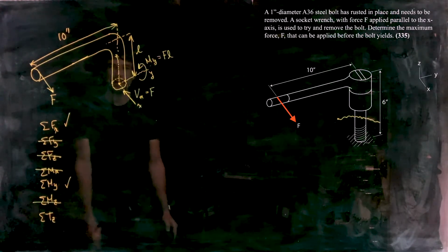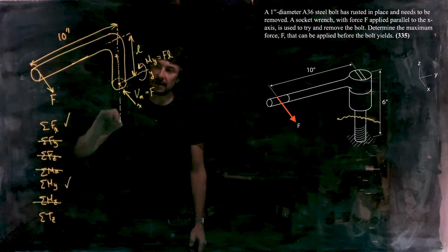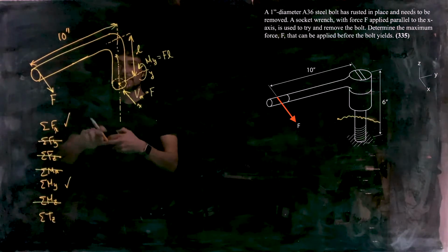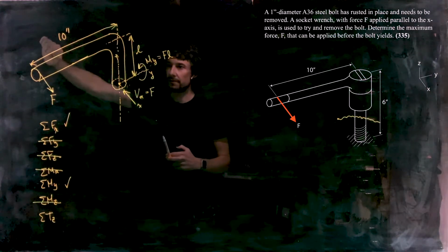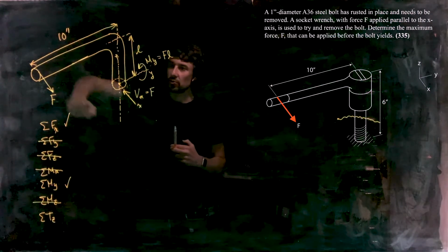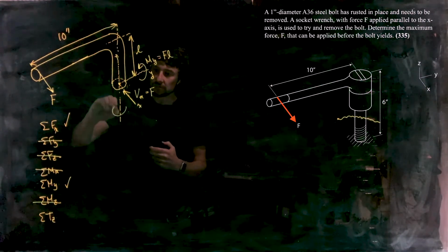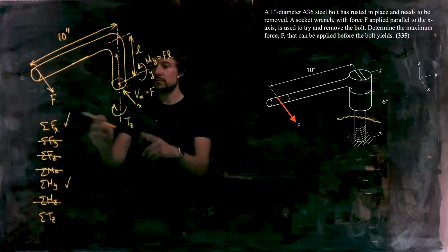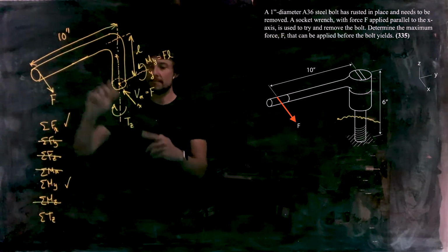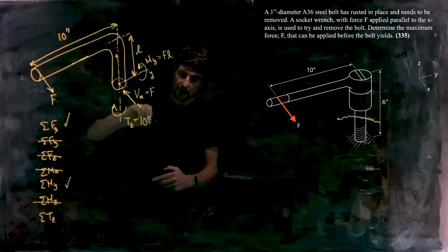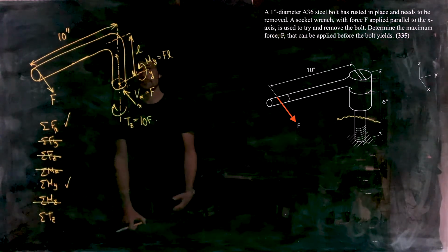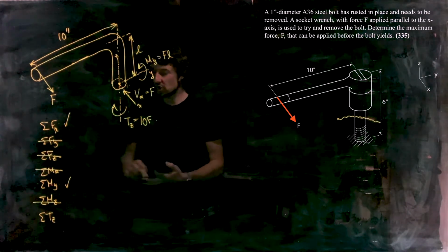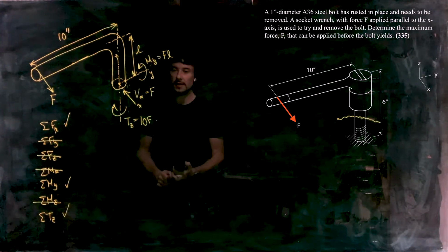The torque about the Z-axis. Let's continue this Z-axis down a little bit. Force is perpendicular to the Z-axis. The two don't meet in three-dimensional space, so the force is going to cause the whole object to want to rotate about the Z-axis this way, so we need an opposite torque, Tz, like this. What's its value going to be? It's going to be the force multiplied by 10, so 10F. There we go.